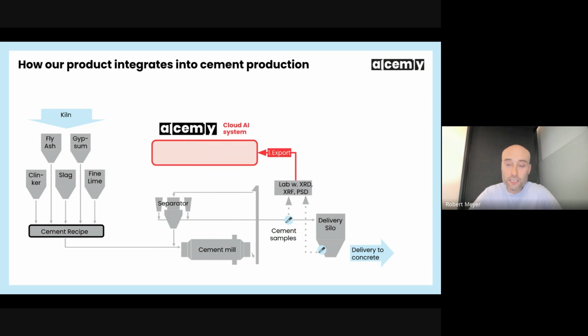So we take this laboratory data, XRD, XRF, and PSD, export this into the cloud, run a prediction algorithm that basically takes this data and then makes a prediction based on the mineralogical chemical composition and the particle size distribution to make a prediction of the resulting 28-day strength of that material, in case you would take that, form a concrete cube, and let it sit and harden for 28 days and crush it.